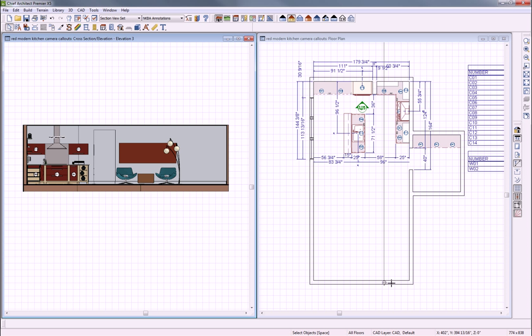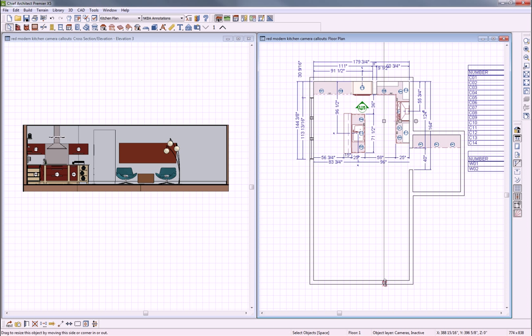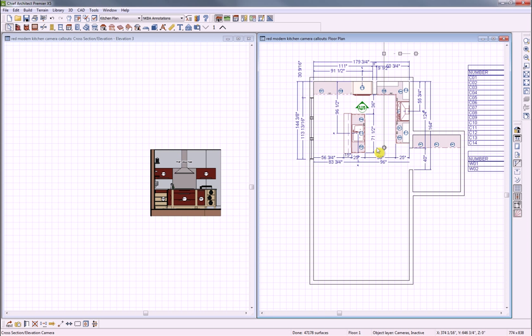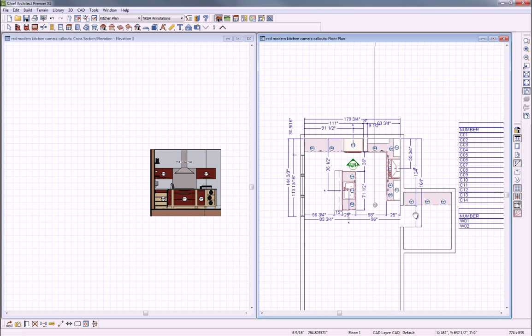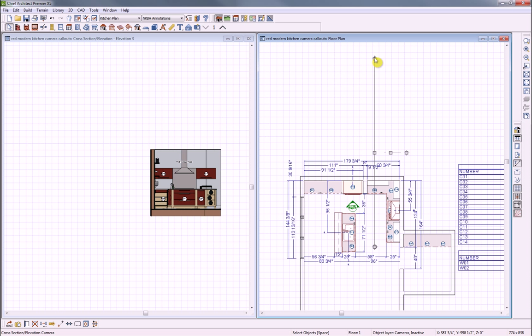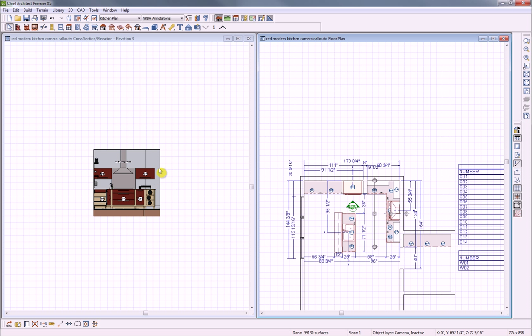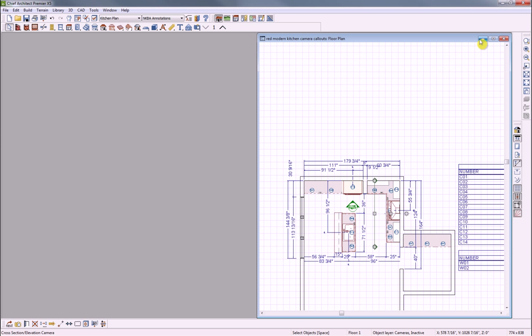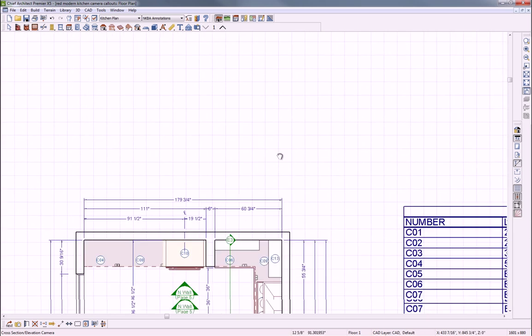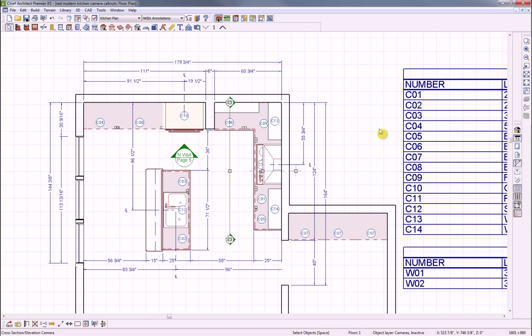So now we can go over to our plan view and we'll click on these callouts, and since we chose to clip it to the side, we can bring that over and line that up with our wall there, so that clips that nicely. And I'll just pan down so we can pull this call out down as well. And we'll clip that right to that wall so we get that nice clip section view right there. And we'll go ahead and click OK. We can close that. And there, I'll expand my view. And there we have our callouts.